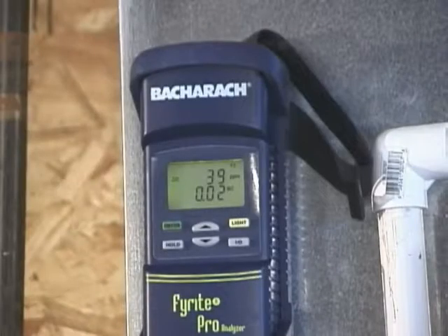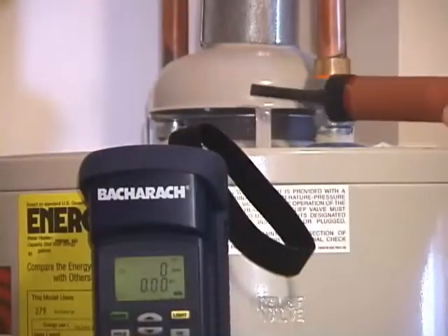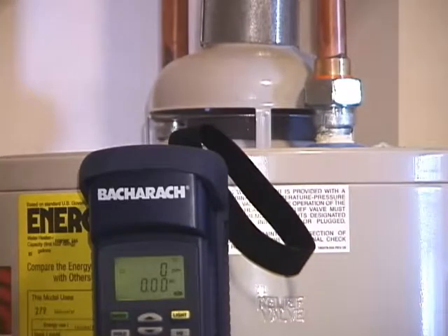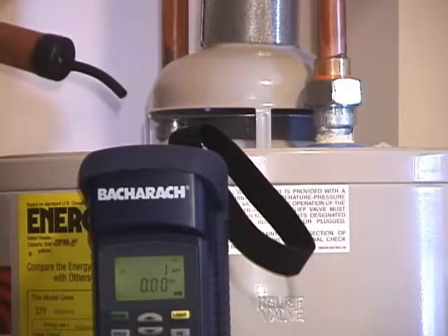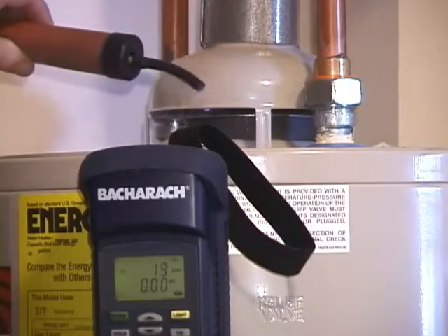We see the same phenomenon of spillage occurs here. As the furnace fires, we see the pressure in the vent connector is a positive 0.02 inches of water column. And checking the water heater draft hood with the smoke puffer shows total spillage. We also repeated this test with the water heater already fired for 2 minutes before we fired the furnace. We see once again that we have total spillage at the draft hood.